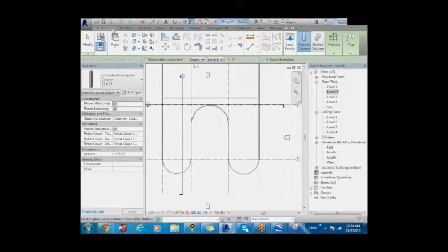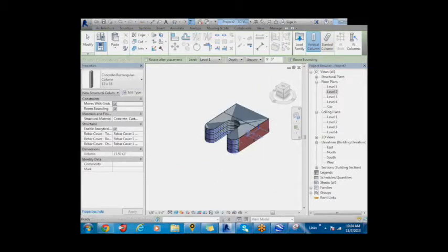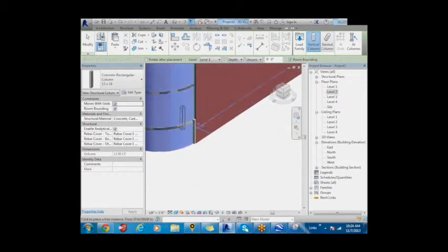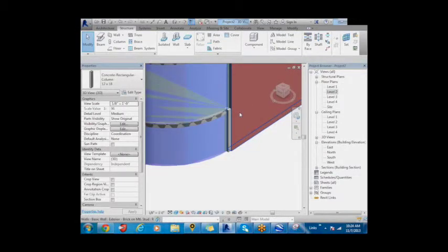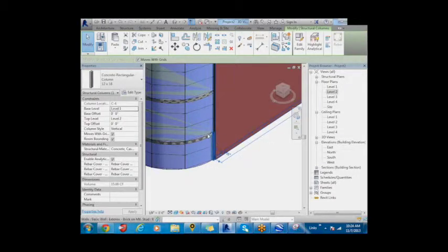All right, so let's take a look at it in 3D view. Yeah, so this is what I was trying to avoid. You typically don't want columns here. For columns, you also have the option to select it, and then you could make the column go from the bottom level to the top level 5 if you wanted to. All you have to do is change the top level constraint. That would make your work easier. You could do that if you're not really focused on the actual design.